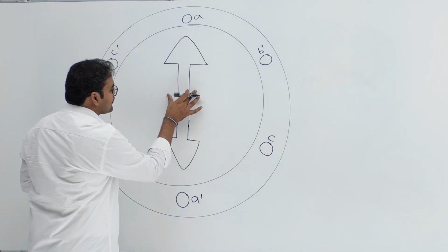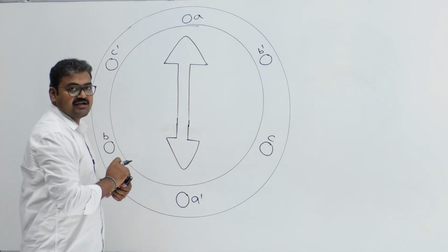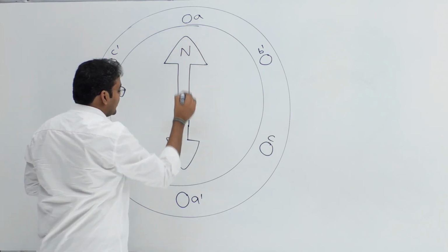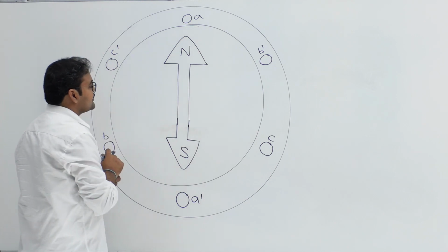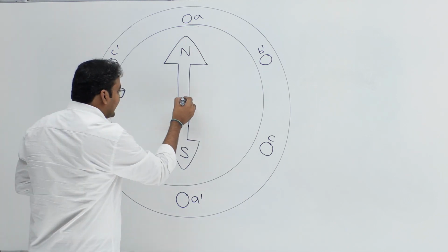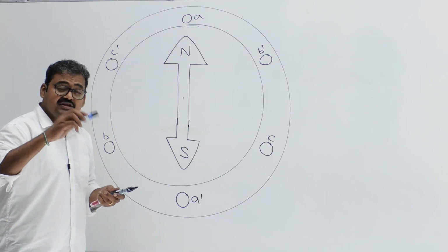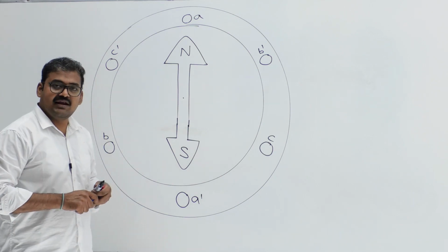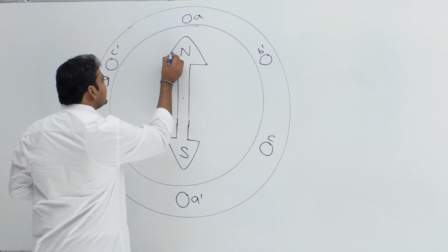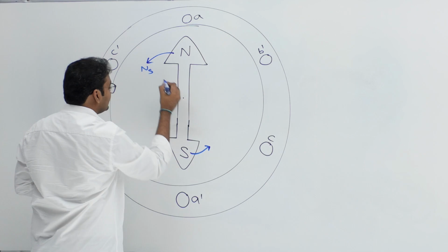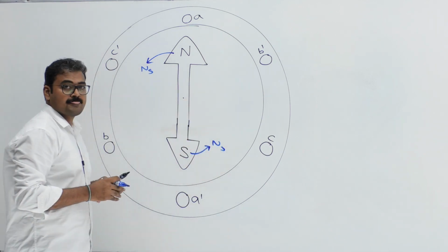We will excite this rotor with DC supply or AC supply. DC supply, and assume that DC supply created north pole here and south pole here. And as it is a rotor, we have to rotate it. You can rotate this rotor in any direction. Let us assume that I am rotating this rotor in anti-clockwise direction at a speed equal to synchronous speed.